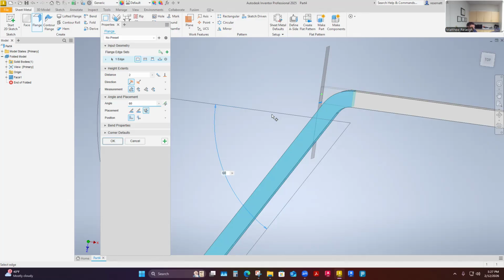And so once we dialed these in for our materials and our machine, we stuck with these measurements: which one I'm measuring with, which one I'm selecting here, which one I'm selecting here, and even the position here. So there was a series of these that we always used that we had dialed into our machine. And I think most companies will do that too. If they've dialed in the machine to these measurements, this placement, this position with these bend properties, then if you change any of those, you're going to have some issues with what they're expecting when they run the machine and get their bend profiles.